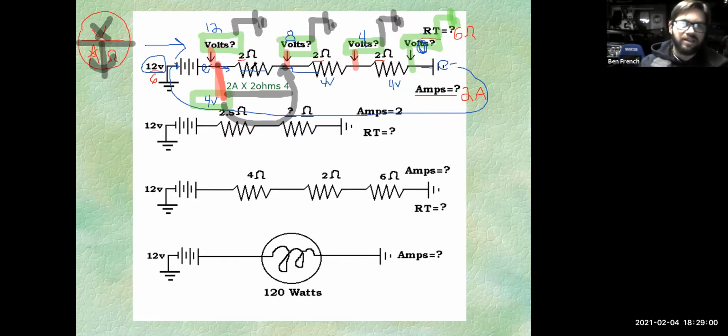Okay. And why I'm pointing this out is sometimes I'll see a student hook up their meter one way, or they'll hook up the meter the other way. And sometimes I've even done it. And I think, wait, that doesn't make any sense. And it's like, oh yeah, it does, dummy. You're not thinking about it right. Look at how you've hooked up your meter. So are you measuring your voltage drop across a component, or across multiple components, or multiple parts of the circuit?